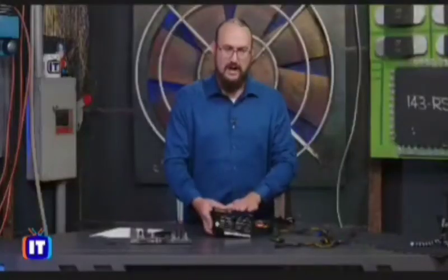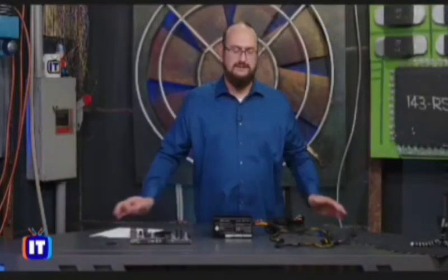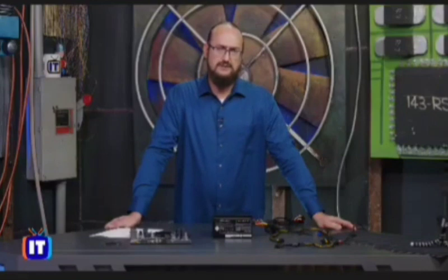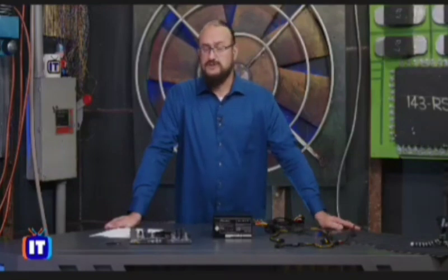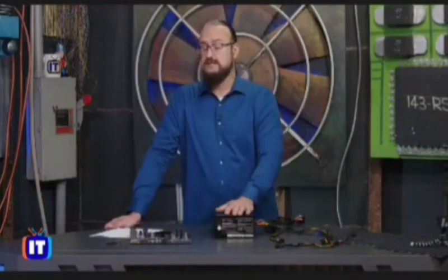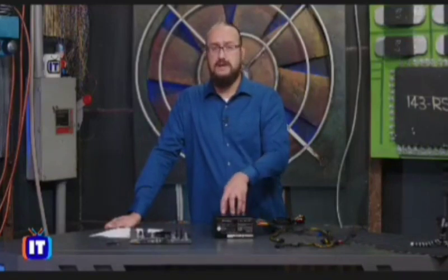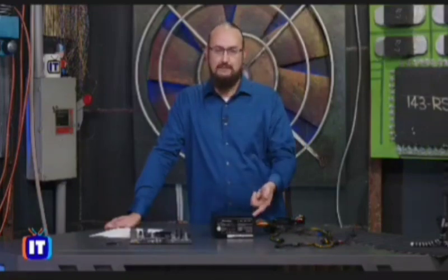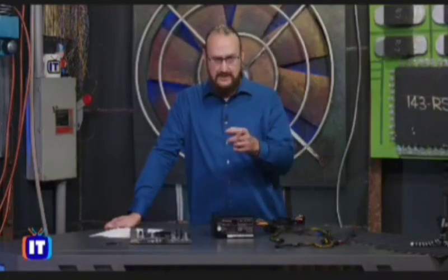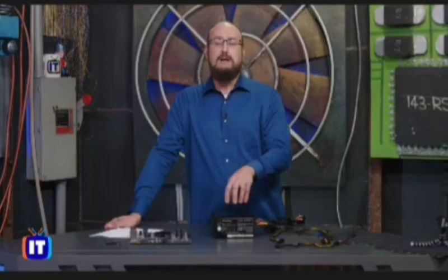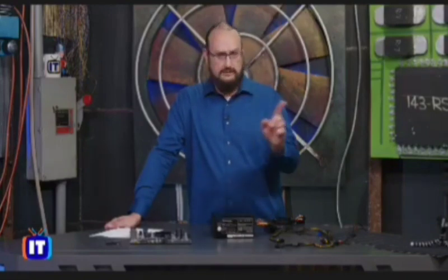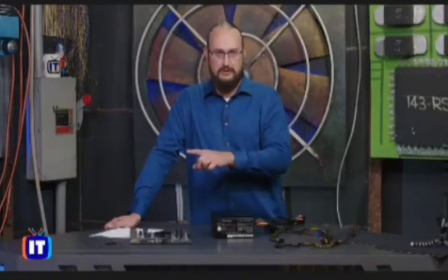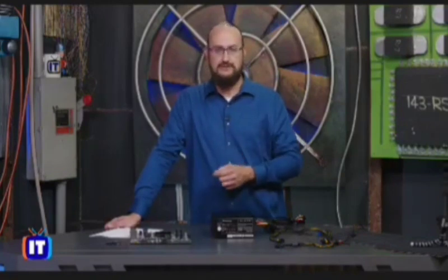So how does this power supply know that we're connected to a 110 or a 115 circuit or a 220 circuit? Well, there's something known as auto switching. This is an auto switching power supply, which means it can detect what the voltage is that it's connected to, and it can make the adjustments appropriately. However, you do have power supplies that you will see on the back of the power supply a little red switch. And this is a fixed input power supply, because what that does, it can still work in both geographical regions. It just means you have to manually flip the switch.